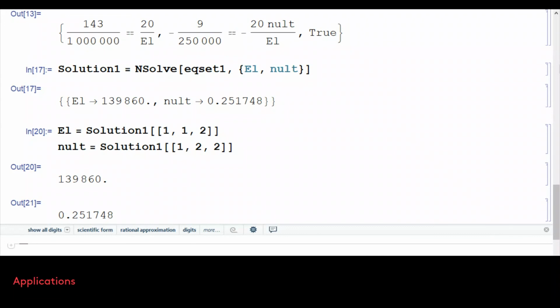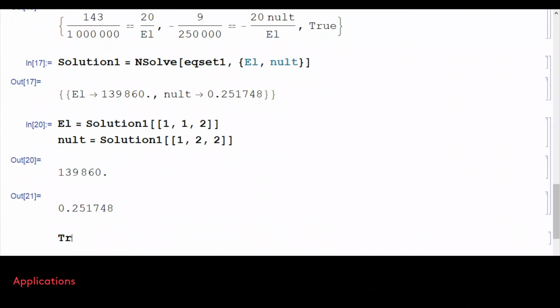So remember that it is the transpose of the transformation matrix, which I already calculated, multiplied by the compliance, multiplied by the T. This is my rotated compliance. Then I will multiply this expression with the stress that is measured.